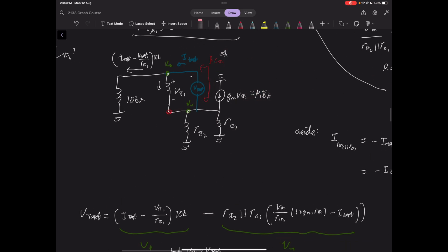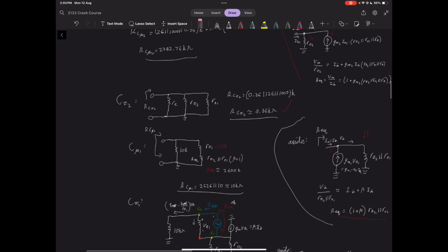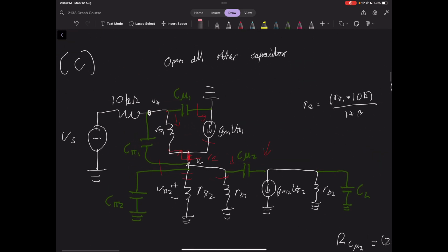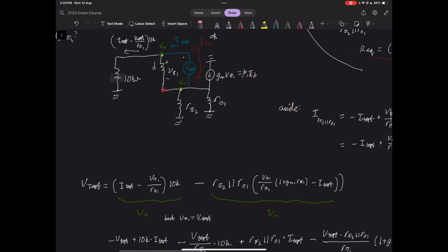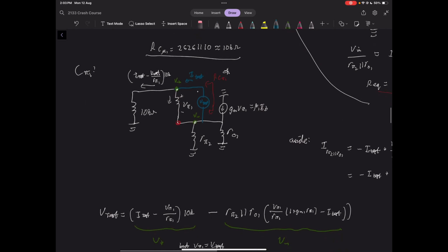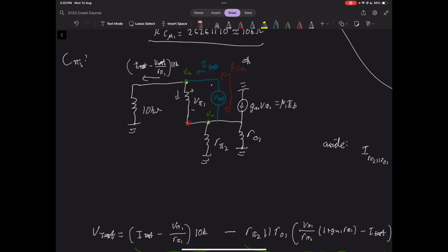This circuit here, we are looking at C pi 1. This one is quite frustrating to do, but you'll notice this node up here, this is what I called V plus, and then let me just try and tidy this up down here. This node down here is what I called V minus. So we're using method 3 again, we turn off our independent sources, we attach a test voltage source here,